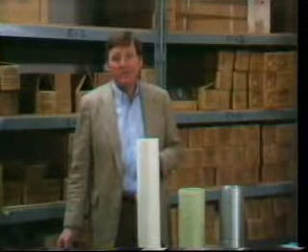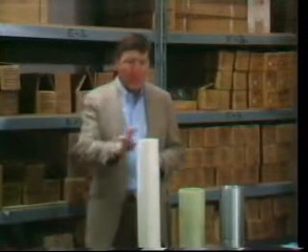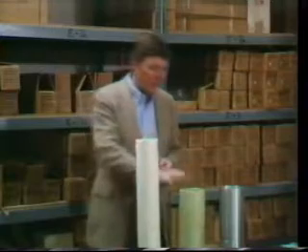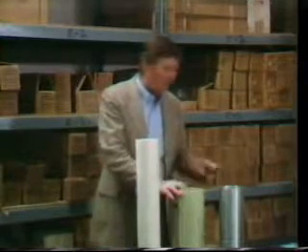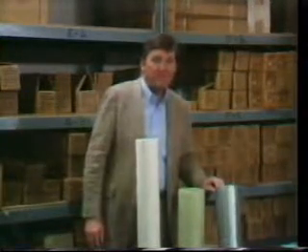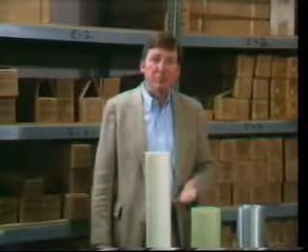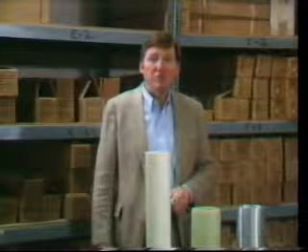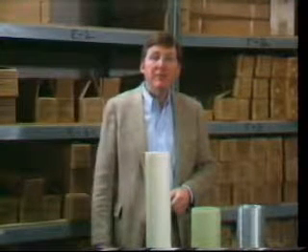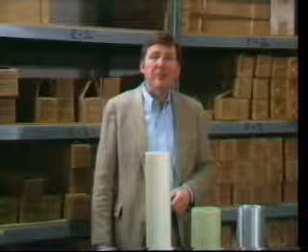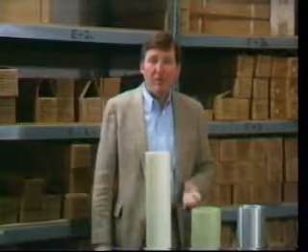Here we see examples of a rubber sleeve, plastic liner, fiberglass inner barrel, and aluminum inner barrel. In Canada's tar sands, we typically use plastic liners and freeze the core in the liner at the well site. There are two more devices that can be used during conventional coring, the pressure core barrel and the sponge core barrel. Before discussing them, though, let's be sure we understand the concept of filtrate invasion and blowdown.